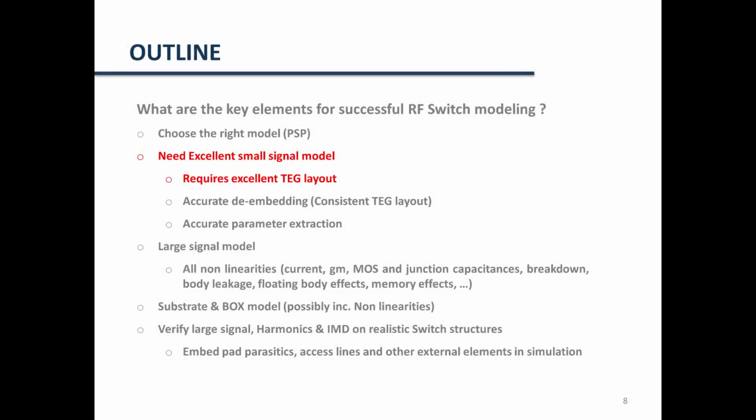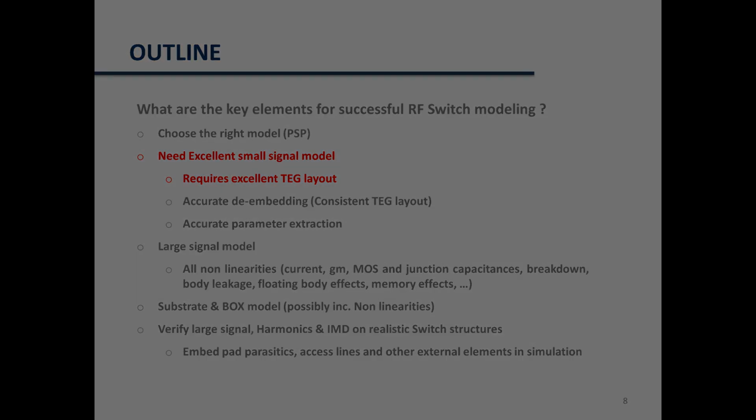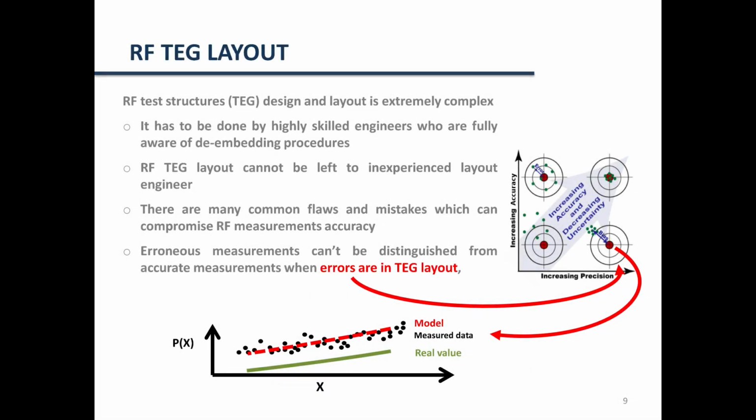We need an excellent small signal model in order to build our RF switch model. And in order to do that, it's important to have excellent test structure layout. RF test structure layout is extremely complex. It has to be done by highly skilled engineers who are fully aware of the embedding procedures. RF test structures cannot be left to inexperienced layout engineers, because there are many common flaws and mistakes which can compromise the RF measurement accuracy.